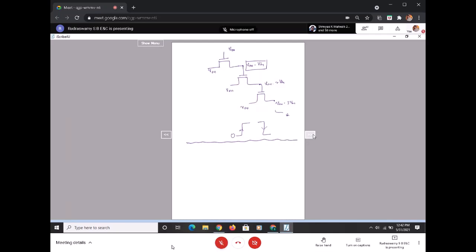Now, we are using a capacitance here, exactly this capacitance. Can we have an active capacitance rather than a passive capacitance? Now we have C boot and CS as passive capacitances. Can we have an active capacitance? We replaced a resistor either by using the PMOS, or by using the NMOS with gate connected to VDD, or we can have a depletion NMOS.